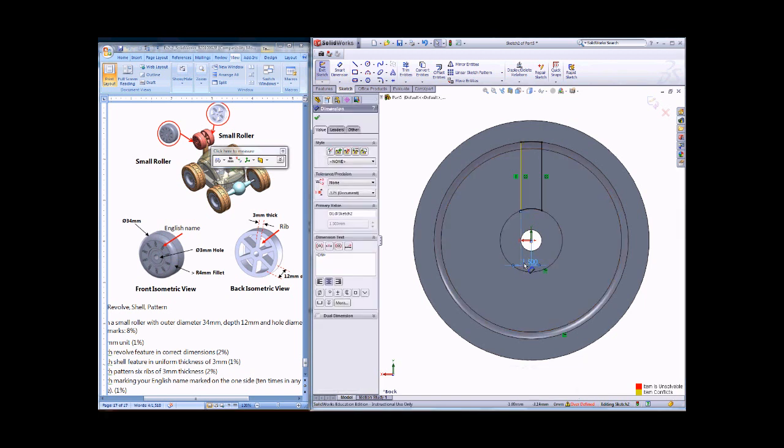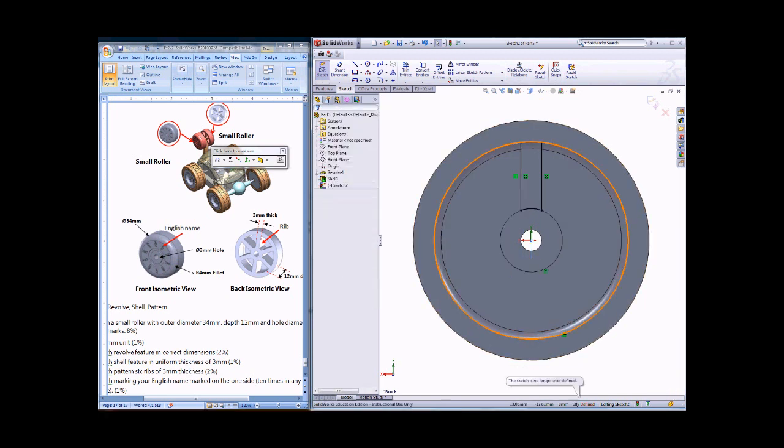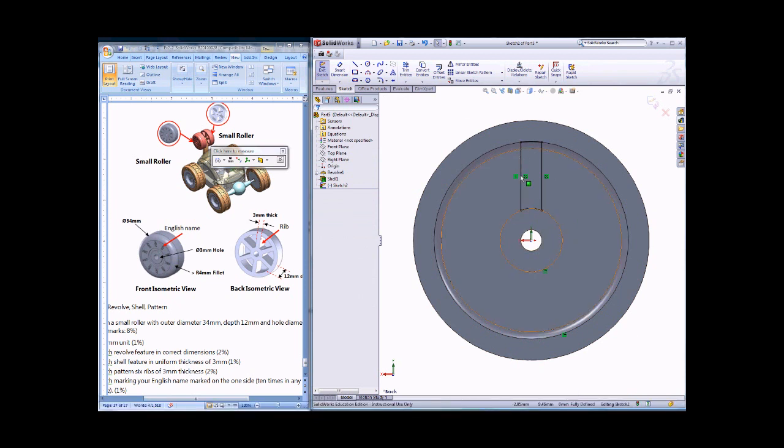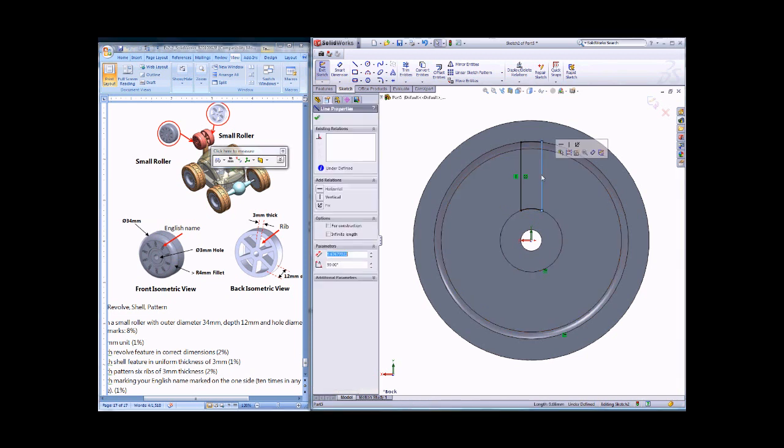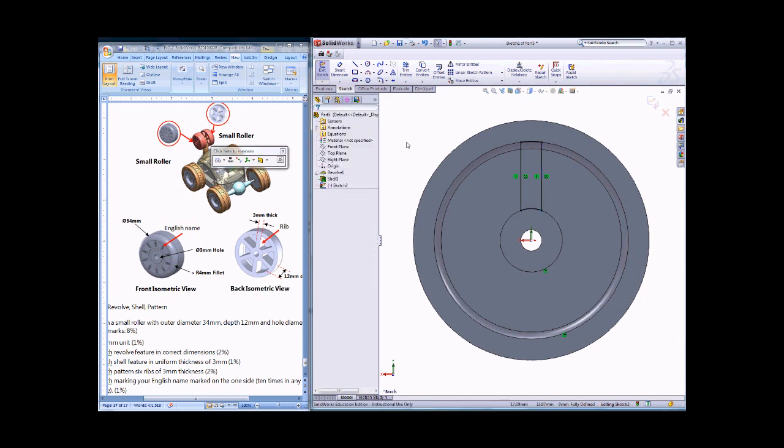I think that one you need to delete it, because over constraint here. So you can see we can use fix vertical or something to control the line, because that one you can use the vertical to control it and then fix it. So the relations, I fix all of the relation right now, and then press the spacebar to change the orientation